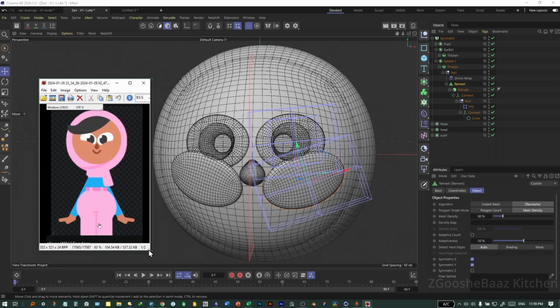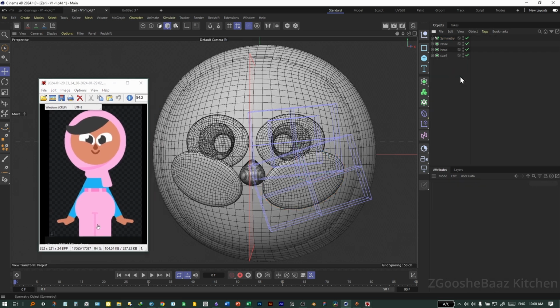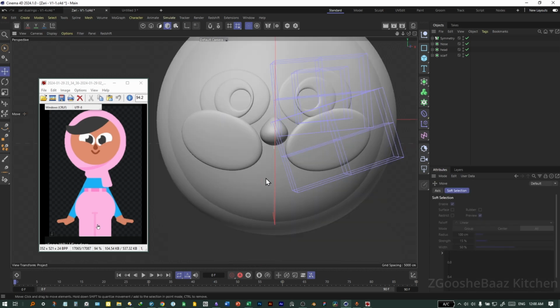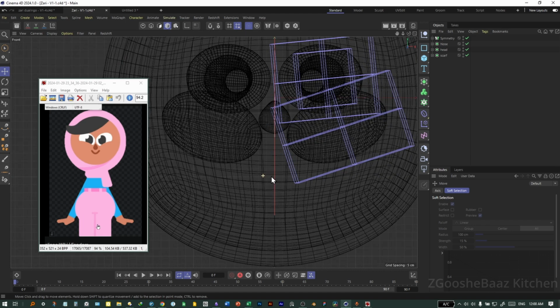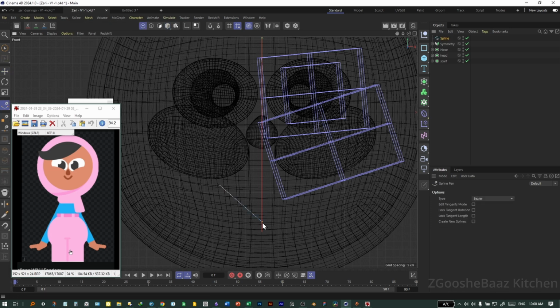Open the reference again. Okay, let's rename eyeball 1 to cheeks. Let's close all this. N A, N A. Okay, let's add the mouth here. For the mouth base spline, let's come to front view, spline, and select the spline pen and click 3 times to make something like this for the mouth. Then hit escape, come back to model mode, select the spline.